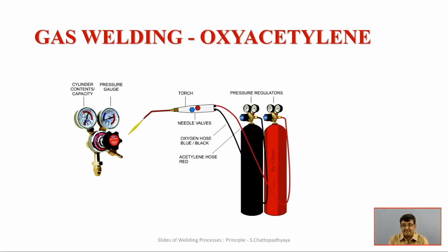This knowledge is crucial. The gases are put into the nozzle where they are mixed, and on that basis delivered with needle valves through the oxygen and acetylene hoses, and with the gauges we can control the delivery. They are ignited, and on that basis the heat is generated.